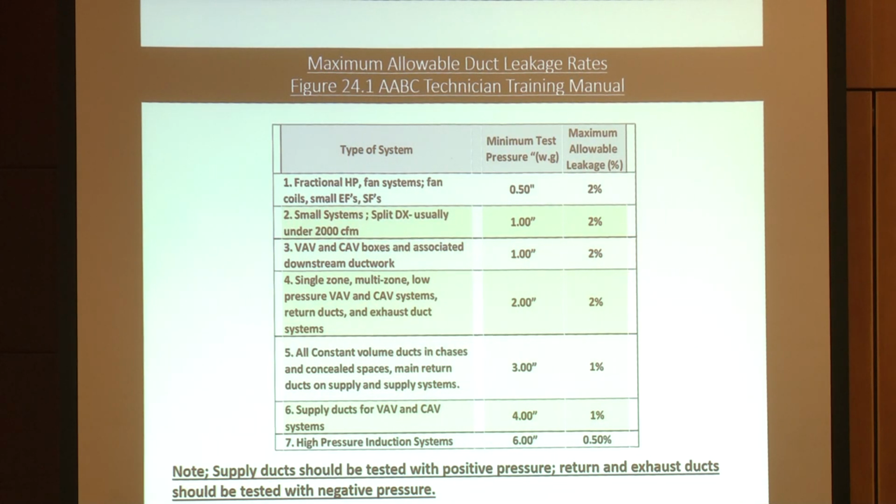So, really quick if they didn't seal it, we have a name for that. We call it Pookie. Have you guys ever heard of Pookie? Pookie is the duct sealant. It's like a gooey goop that you brush on the ducts and it seals. It dries hard and it seals the duct. But that's a hard job, because you've got to get up on a ladder or a lift and you've got to go do all the duct, and it's a very hard and long process.